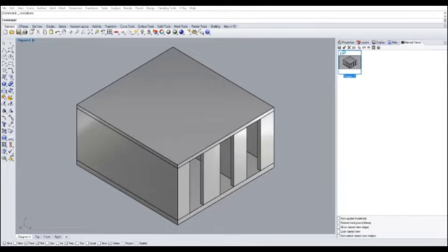Now, some of you might be thinking, well, the color says it's black in here, but that color doesn't correspond to the solid 3D geometry. It's only responding to the outline of this material, and that outline of this material is black. So in fact, if you also change those materials, see, the outline of that material hasn't changed. Please keep it to black for this initial range. So what we have now is two different types of render material called tune and generic. What we're going to ultimately assign to this will be a series of these two, but with different colors.